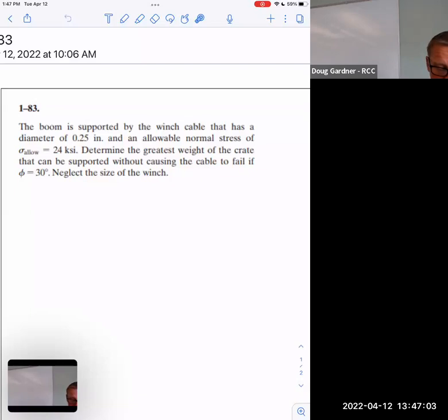Now, KSI, is that 1,000 pounds? Yeah, 24 KSI. The K is 1,000. So it's really thousands. So this is actually 24,000 PSI. It should say KPSI. You see what I'm saying? There's a number of things like this that are just weird. There's all kinds of stuff. K means other things. Every letter in the alphabet gets used in a class like this. And of course, that's something you're going to see a lot, because in any real project you work on, I've told you this is never going to be in pounds, because nothing ever lifts pounds. It lifts thousands of pounds. And so they just try to make it simpler. So it's always kips. And anyway, so we know this thing's 30 degrees.